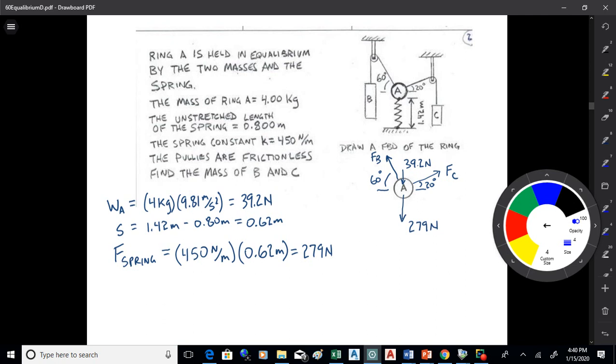All right. So now we've got two unknowns. I don't know what those cable forces are, but the good news is I've got two directions. Forces are vectors. I've got an x direction and a y direction, so I have two equations I can generate, one based on x and the other based on y. So I have two unknowns, so I should be able to solve this. So we good on the free body diagram? We good?